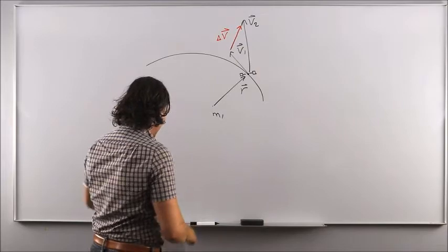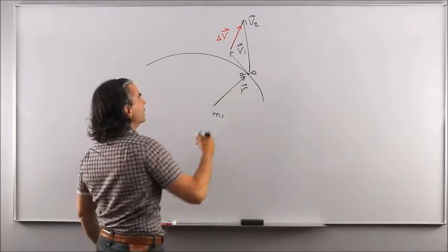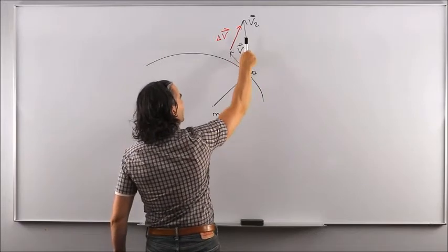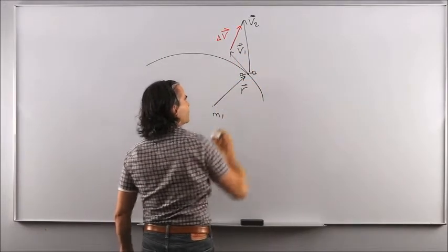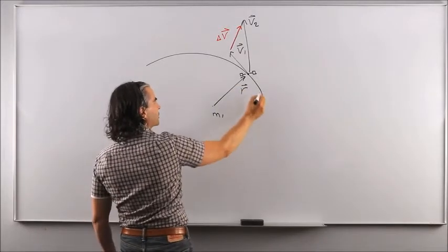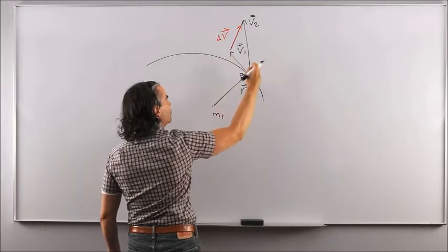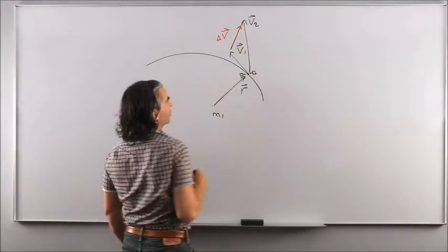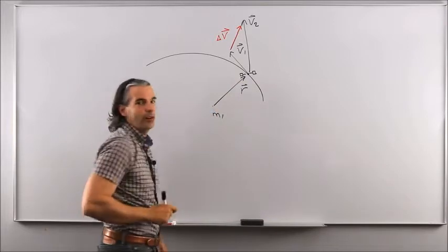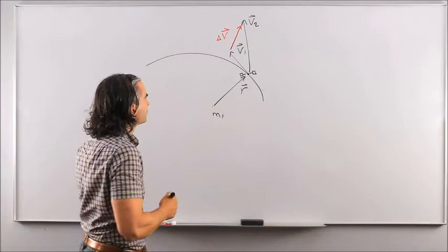Notice that within the impulsive orbital maneuver assumption, the change in velocity happens at the same orbital position vector. The spacecraft was at r vector traveling with v1, and boom, all of a sudden its velocity jumped to v2 at the same position vector. This is the impulsive maneuver assumption with which we're going to begin this chapter.